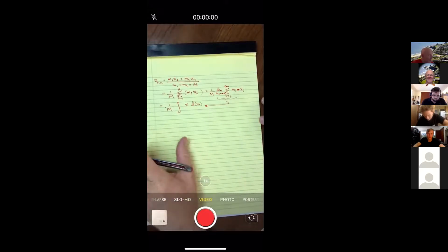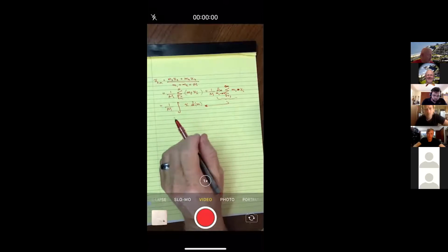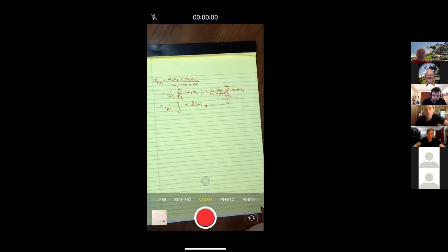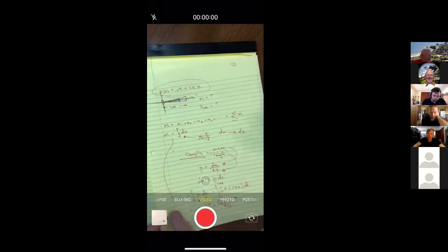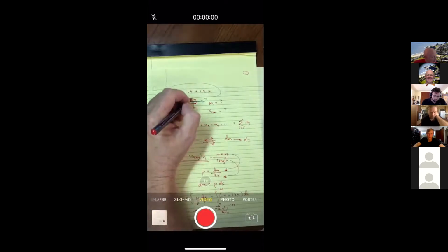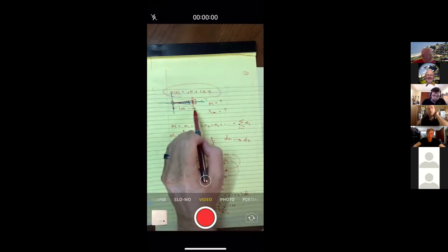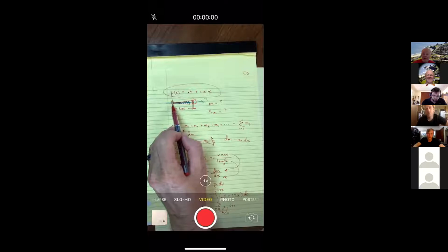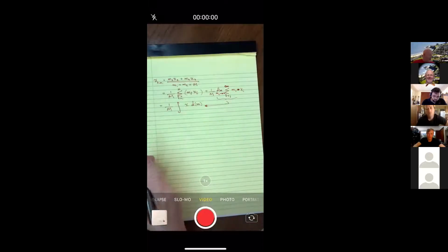I think there's a big temptation in this step to call this dx, because in our math class, you always had dx. But please remember that in your math class, x did not mean the x-axis. It just meant a variable. Something was going to 0. It's not necessarily the x-axis that's going to 0. And going back to this baseball bat, when I make this slice out here thinner and thinner, I'm not saying its position is going to 0. That would be like saying its position is way over here at the handle of the bat. No. It's not the position that is going to 0. It's that the mass is going to 0.